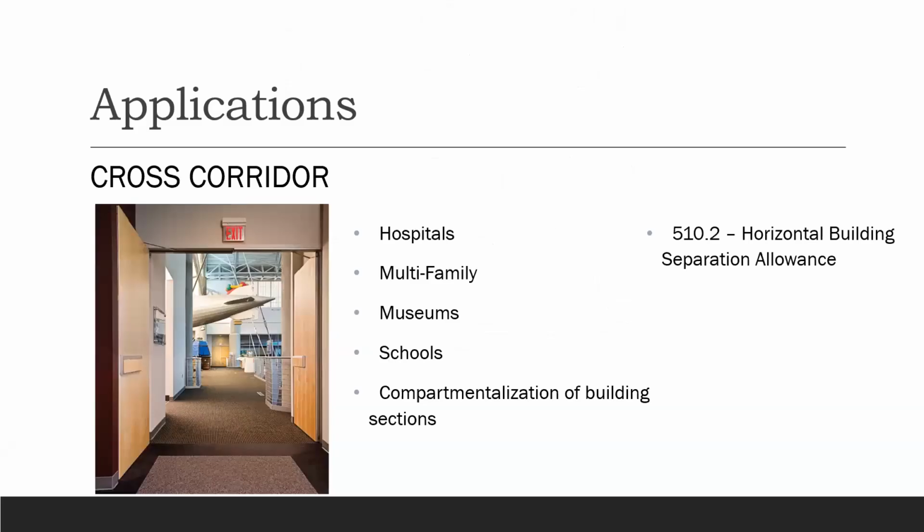So the purpose of cross-corridor doors is to compartmentalize areas of a building. Now, the very last thing we would want is to route someone into another smoky area. And if there was really no way to get out of the building, there needs to be a way to compartmentalize the area that's burning from your safe space. And these cannot be just fire doors. Why is that? If they were, you may not burn, but you would inhale all the smoke.